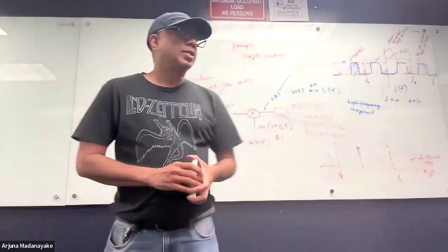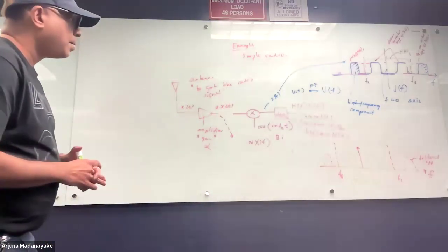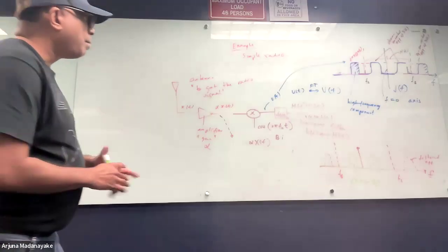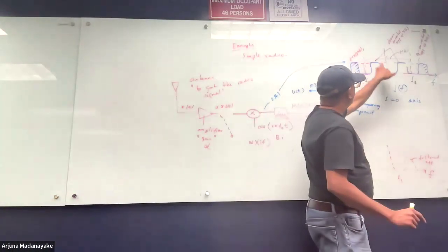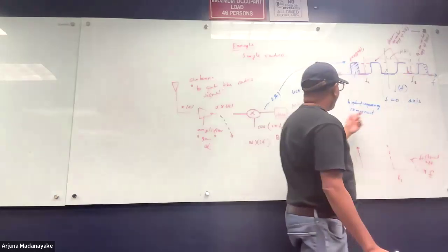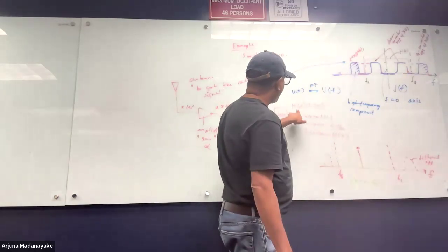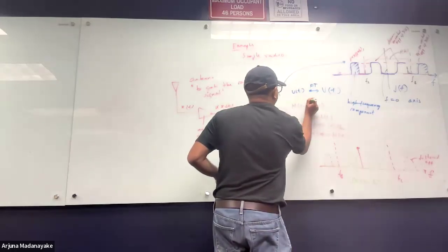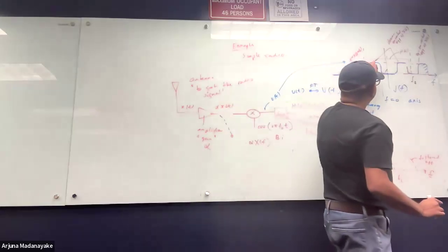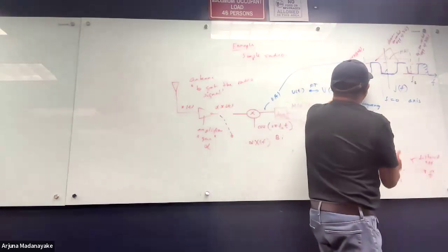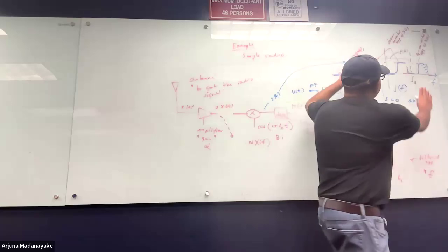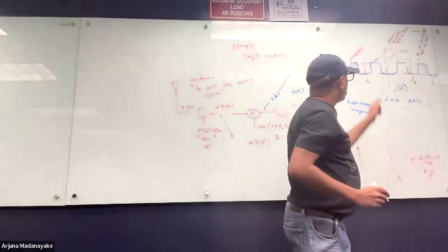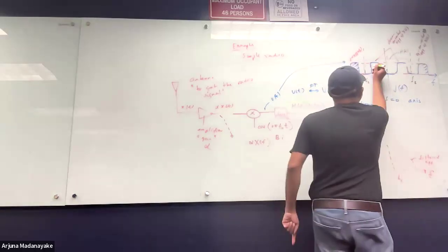I have a question. Yes. For the bottom graph, I know you kept the low frequencies, but you drew a box h of t. Why don't you draw a box down there? Because the box is multiplying with this blue function. Remember, we are multiplying. So h of f times, this box is something like this. When you multiply this blue function with the box, there's 0 here. So it chops off these two ears, but it keeps this central part. That central part is this. So this is my green.